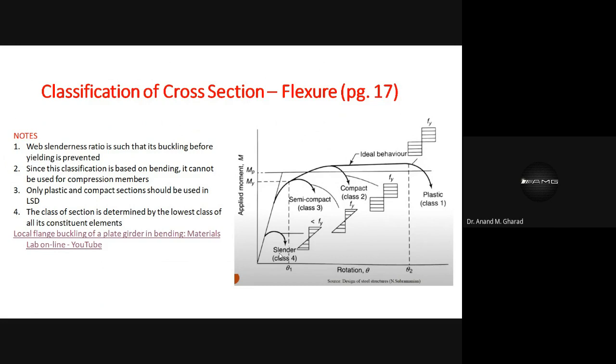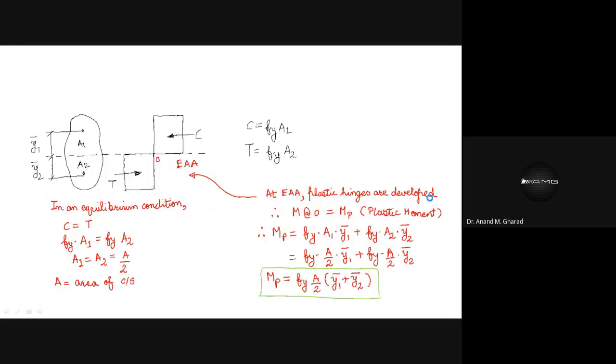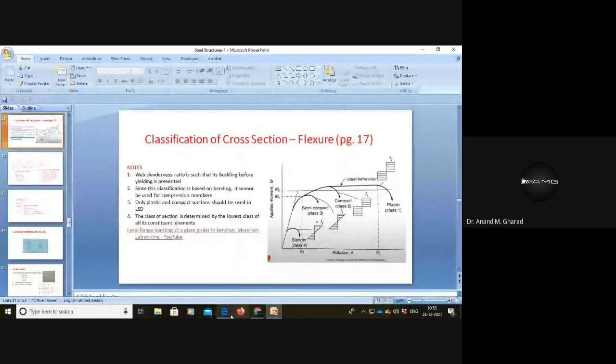Even with smaller loads also, sometimes it may happen that the sections are very poor, based on which the local buckling can occur in the earlier stage itself, and those sections are our slender sections. We want to avoid all these things. That means we are supposed to avoid the local buckling phenomena initially in order to achieve these two stages or two behaviors. Have you understood this thing to some extent?